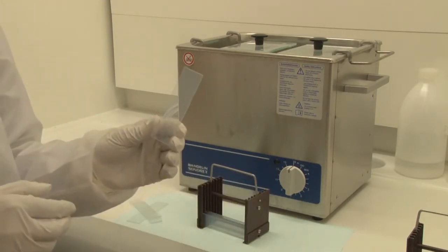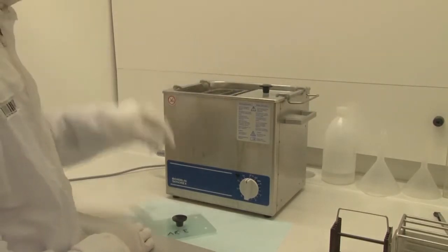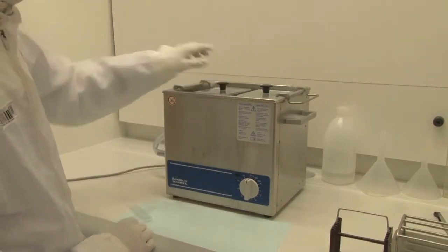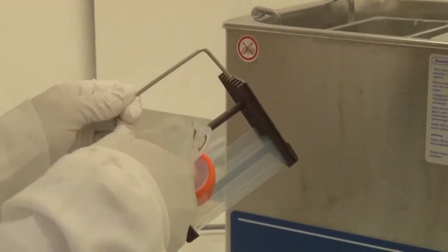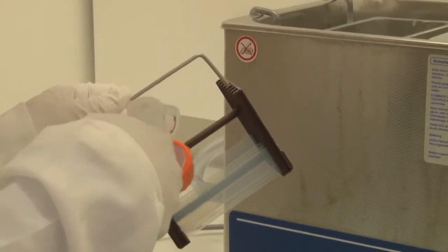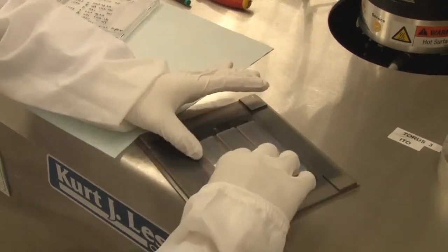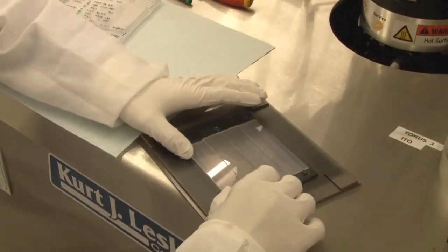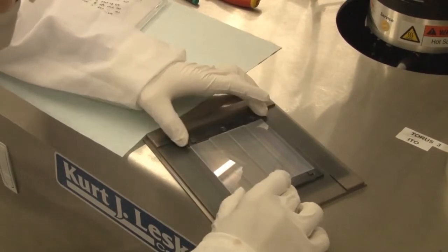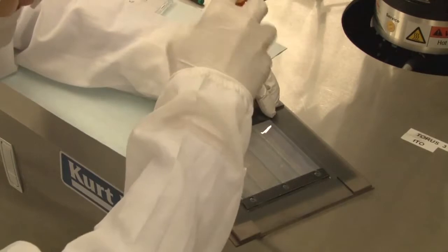Before deposition, the samples have to be cleaned in a so-called ultrasonic cleaning bath. The potential dirt and dust particles are removed. Since the solar cell device is only several hundreds of nanometers up to a few microns thick, a dust particle on the substrate will generate a shunt between the front and back contact in the final solar cell. Here we use a substrate that comes from the Japanese Asahi Glass company and already has a TCO coating on it. The TCO coating is a fluorine doped tin oxide and is responsible for the hazy color.